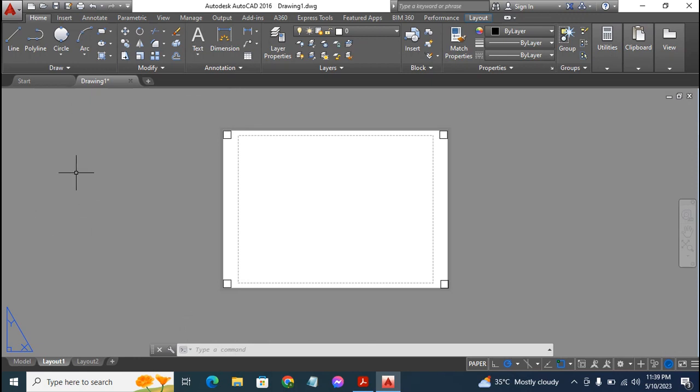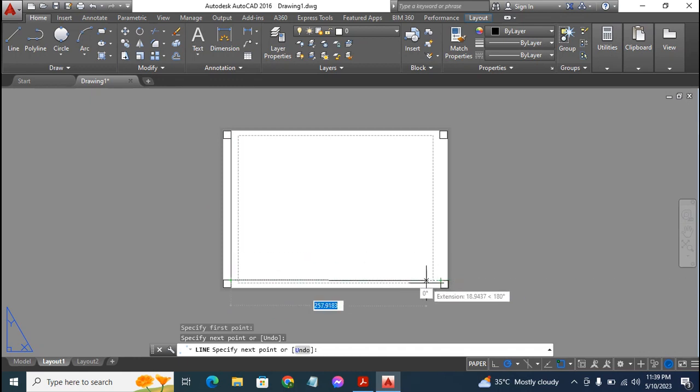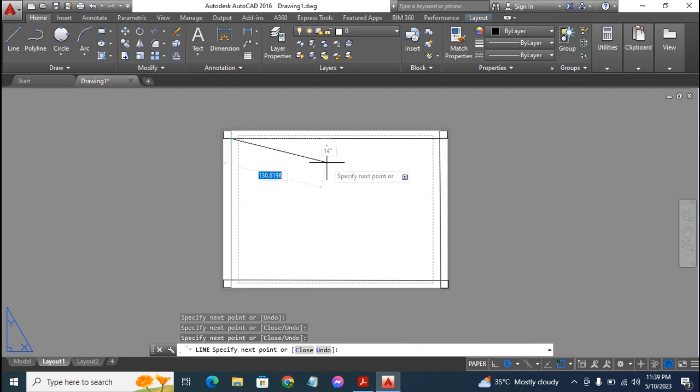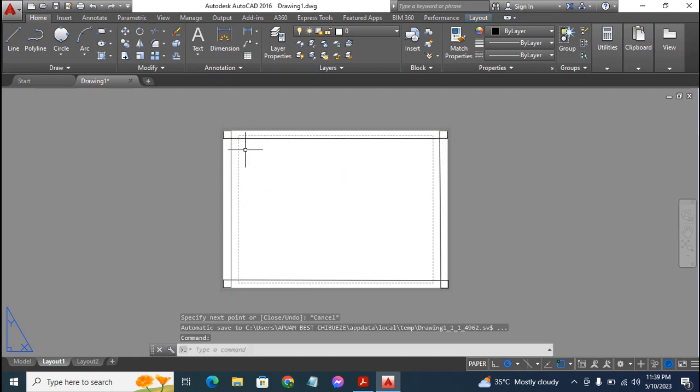So next up, you go to draw, click line on the draw toolbar, then you lock your cursor to the edge of this square, then join these edges of the squares together to get our border line, just exactly as I'm doing it. Lock it to this point of selection. Now we've gotten our border lines.